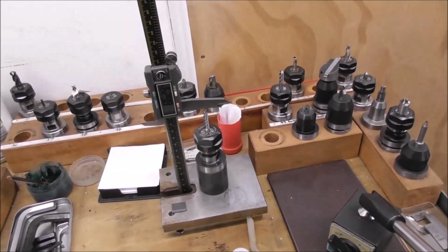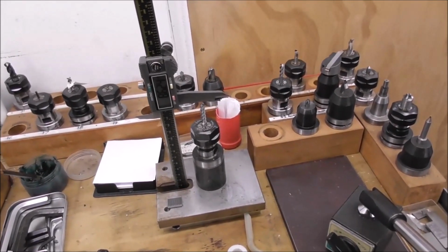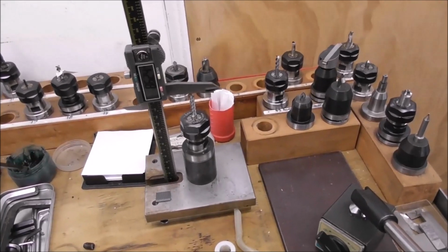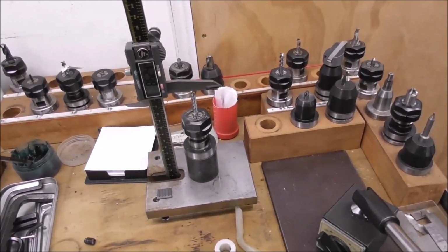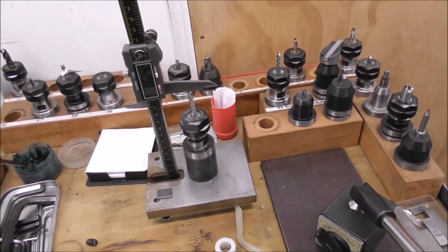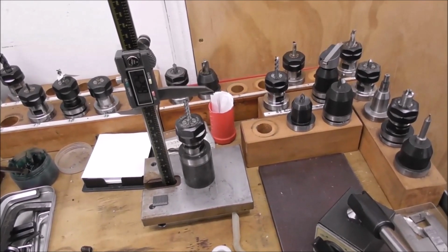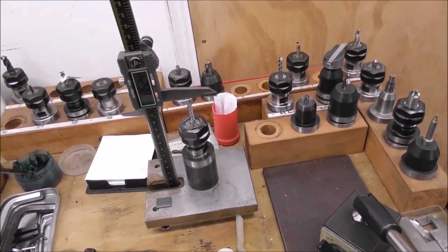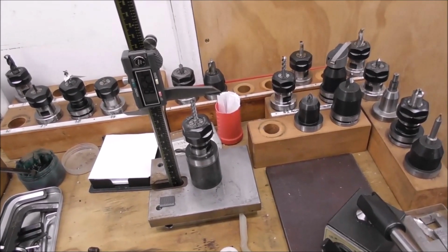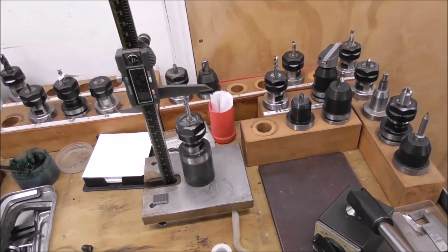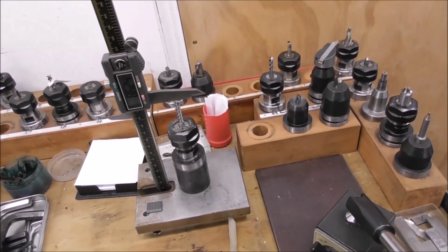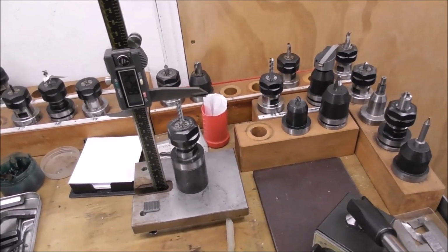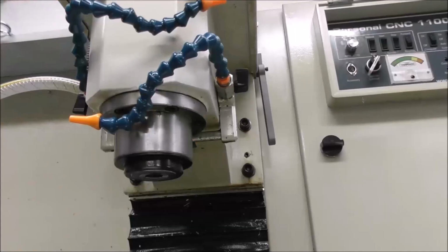So you can see with this example of off-machine tool length measurement, it's not that accurate, and it's fine for drills or roughing cutters, but if you're doing precision work, you'd need to take a test cut and refine the setting, or do the first part set a little shallow, measure it and make an adjustment in order to do high precision work using a low precision tool length measurement system.